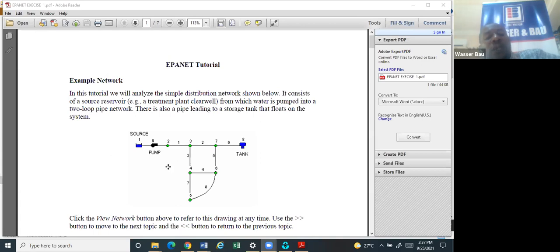Okay. Now, so this pipe is also supplying water to this tank. So the idea is what they do in most states, even in Abuja. Now look at the idea. The idea is that when you're pumping water, these people will have their own overhead tanks. So water will fill their whole overhead tank and also fill the main tank. Then you stop your pump. When their water level goes down, water will flow from this overhead tank back into their system. Okay? But ideally, this is what most networks look like. Most networks will be this way.